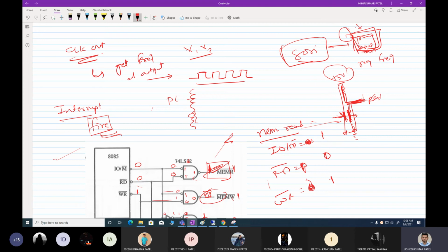Like how the interrupt way works. So using the interrupt way, what we are doing is, rather than raising the hand, the student will interrupt me by asking a question like, "Sir, I have a doubt." So my immediate attention would be there. I stop at the blackboard and return to the students, asking, what's your problem? So interrupt is just that kind of signal. A fire alarm or any kind of priority signal that has to be handled immediately can be assigned to 8085 using this interrupt signal.